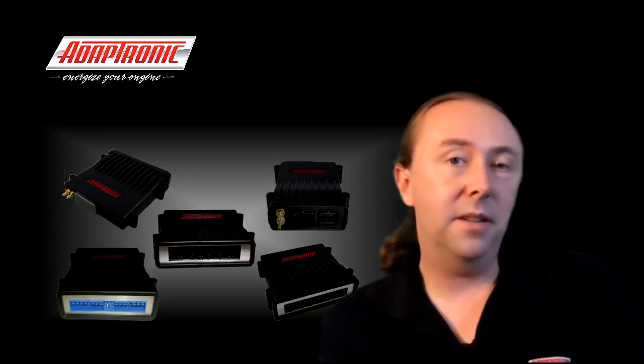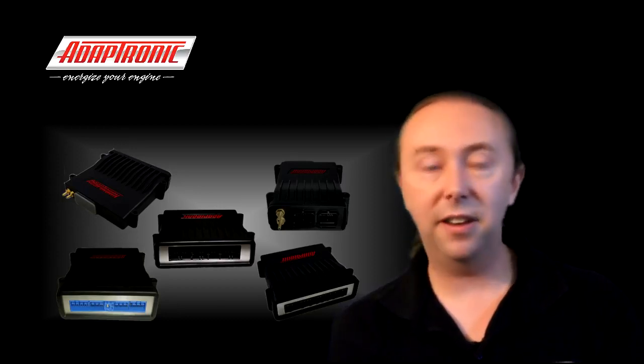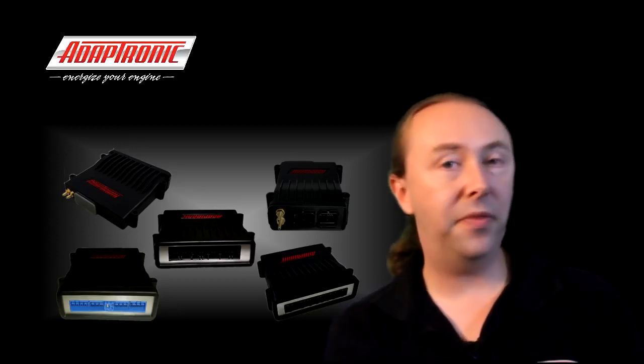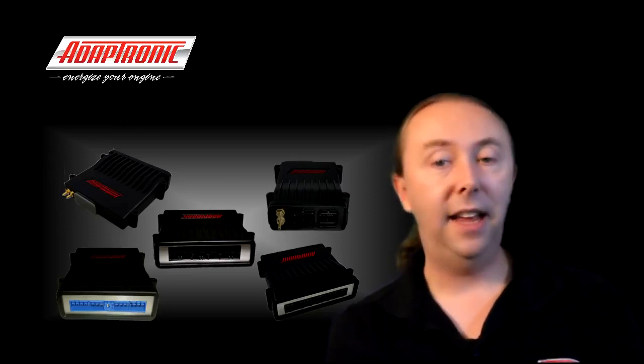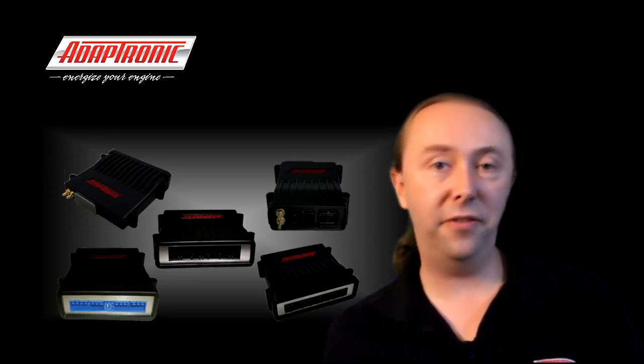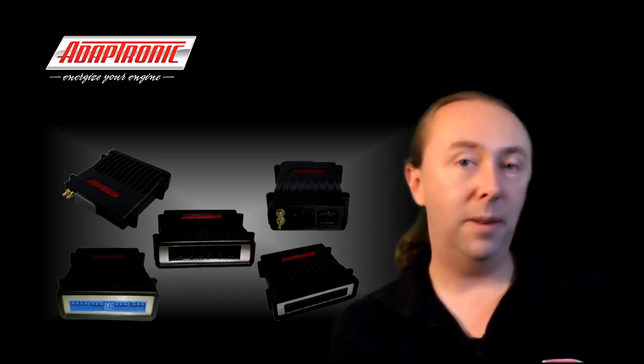So, and you might be asking the question, well, who cares? I know I've got a decent charging system on my car, it's going to get 14 volts, what's the issue? And the issue is that when the car's cranking, you might only have 9 volts delivered to the injector. And if you've got a modern OEM system with 4 bar of fuel pressure, then you need an injector which is powerful enough to open against that with whatever voltage is available during cranking.